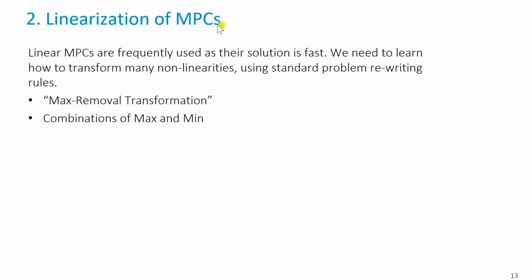Now, when we do this, we will have to do repeated solution of an optimization problem. So the downside of MPC is that it needs to solve optimization problems fairly fast, perhaps not in real time, although some systems are quasi real time, but you will need to do it very fast. So you need to have optimization problems that are relatively tractable. In practice, many MPCs are linear MPCs.